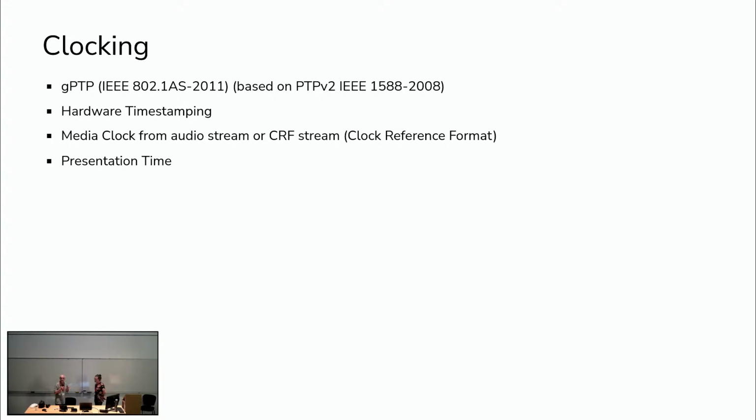That is used internally in AVB: anyone sending packets includes in the packet that it has to be rendered at an exact time in the future, usually 2 milliseconds ahead. So there's time for the packet to get to the destination, and the destination has the same exact time, so it knows, okay, now is the time, and the audio samples go out.